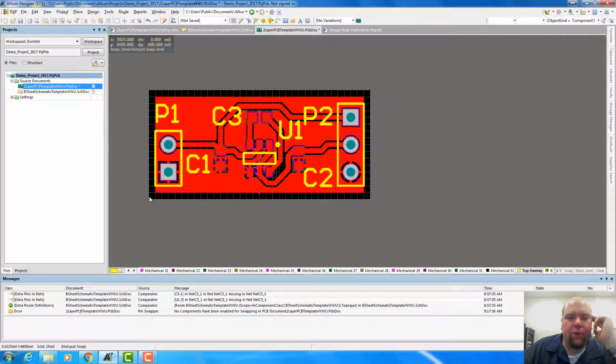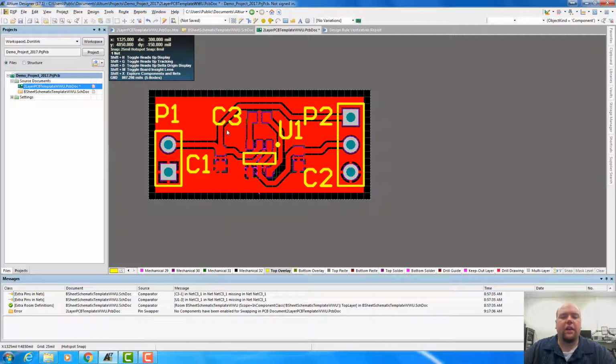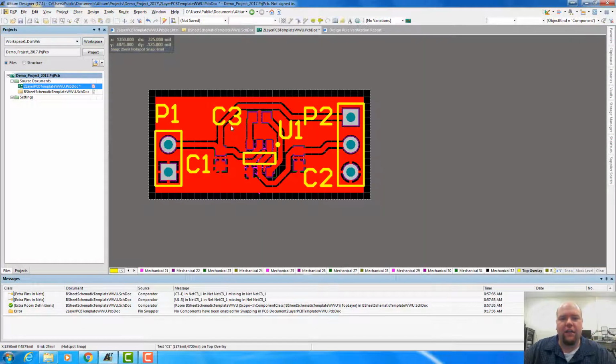So we've defined our board outline, although that doesn't necessarily mean that that's actually our board outline. This is the outline as shown in the software, but when we export this, this Altium board outline is used a lot of times for viewing, for displaying it in your 3D view, the 2D view, and for limiting where routes are. So if you do an auto route, it'll keep the routes within this board area. But it doesn't necessarily tell a fabrication facility where the board outline is. So to do that, we can just specify a keep out.